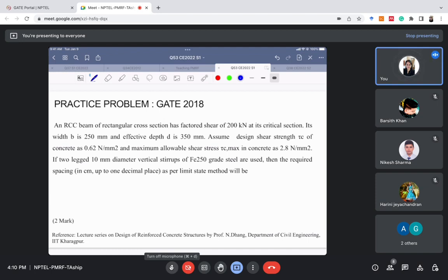I'll give you some time. So a similar question is there. Just follow the same steps I've given you. First of all, find out the nominal shear stress. I'm giving you the formula. The nominal shear stress is VU by BD. And just let me know what value of nominal shear stress you are getting.